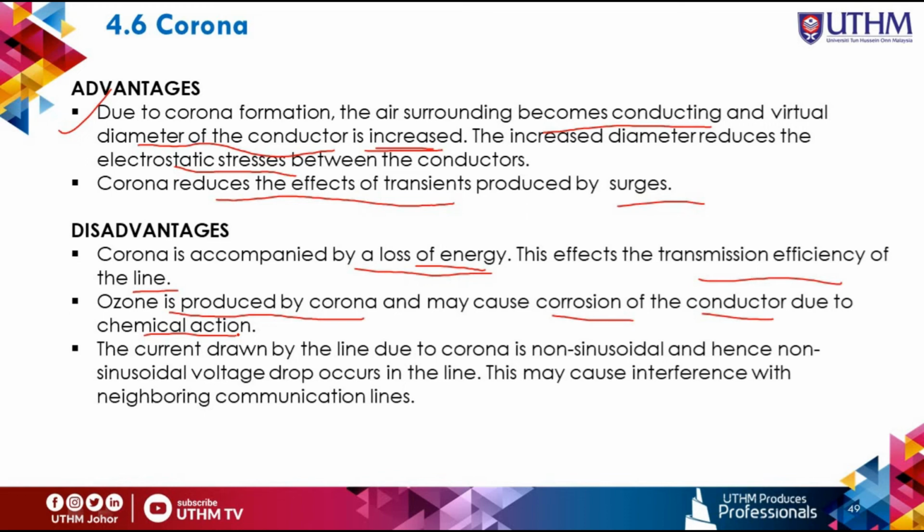Also, the current drawn by the line due to corona is non-sinusoidal, and hence non-sinusoidal voltage drop occurs in the line, and this may cause interference with neighboring communication lines. These are all the advantages and disadvantages of corona.